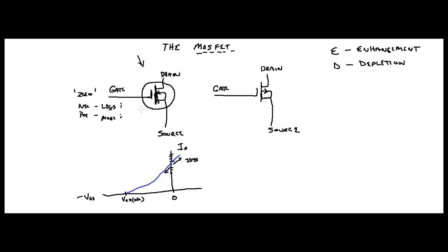So again, these are field effect transistors. Your current here at the gate, I, is very small. That's why these are used so much, because when you create the field there, it doesn't load your circuit. If it doesn't load your circuit, that's a good thing, right? Because that means you don't have to go into extensive designs to take into account a big load, should you have to do that.